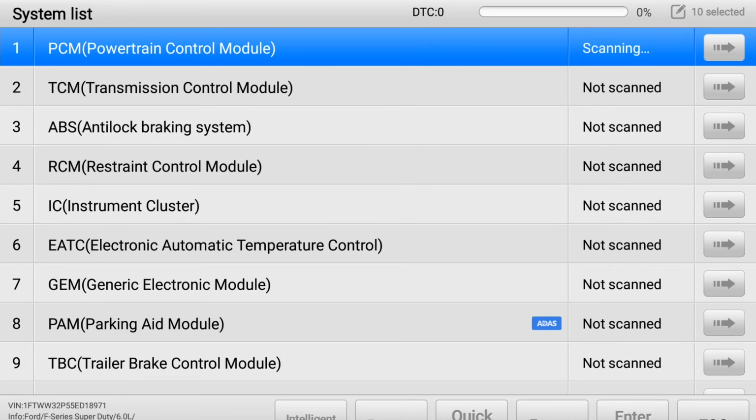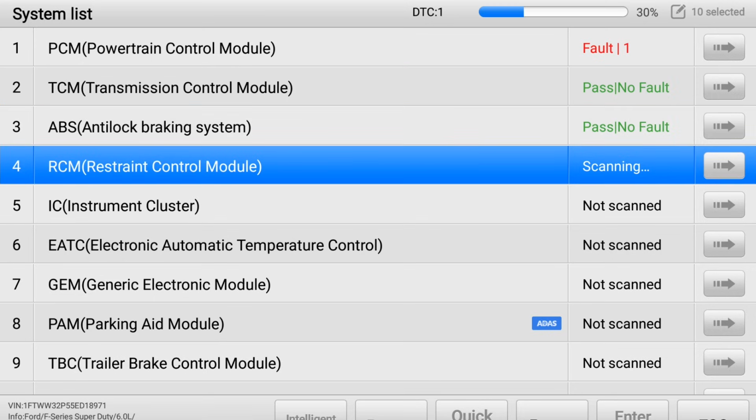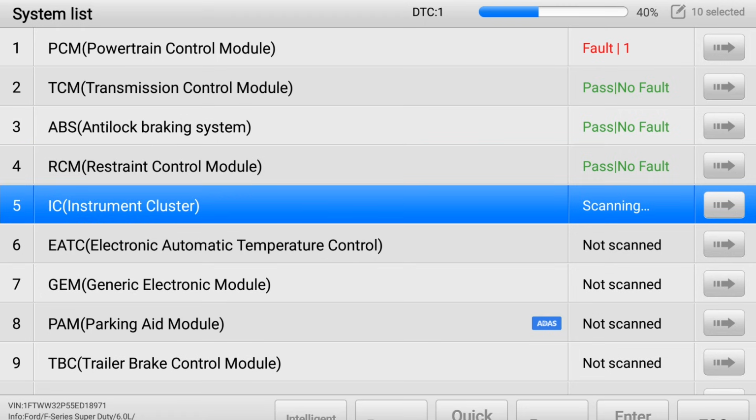Now, whenever you find yourself connecting to a vehicle in enhanced mode, make sure that you perform a full system scan. In other words, while you're hooked up, check every module on the vehicle to see what problems may be stored elsewhere. You never know when a problem in another system may lead you to the cause of the problem in the system that you're troubleshooting. In addition, if you do see systems problems because of that full system scan, it's a good thing to share with your customer so they can make an informed decision about how they want to proceed from there.